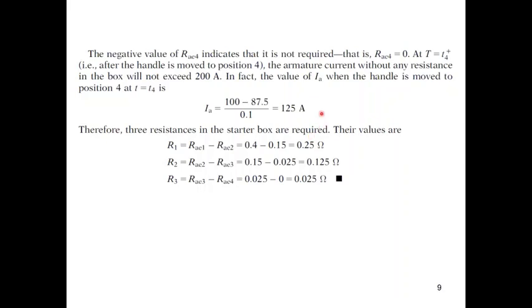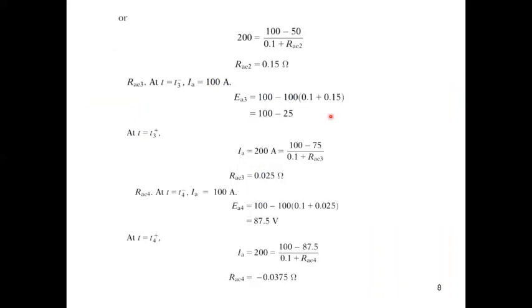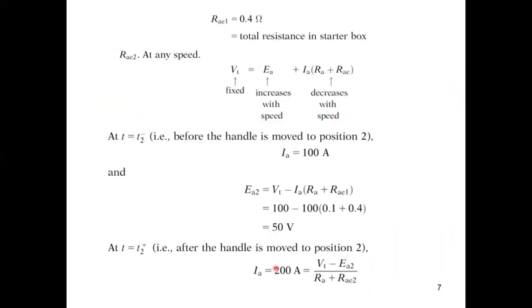How to calculate the speed? Simply, you can go to each step and, using the value of K5, you now know the EMF. So, for example, let's go to step number 2, at T2. We calculated the value of EMF, which was 50 volt. Simply, find K5 from any loading condition.